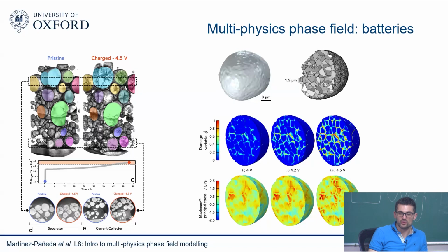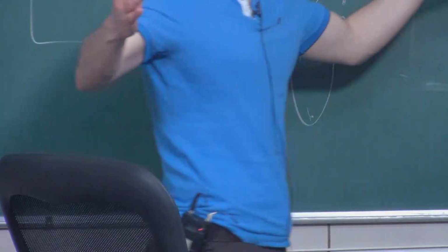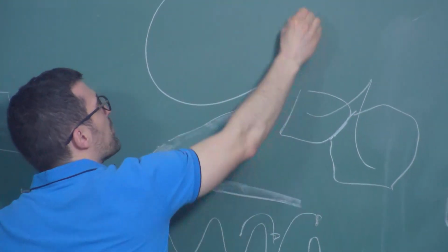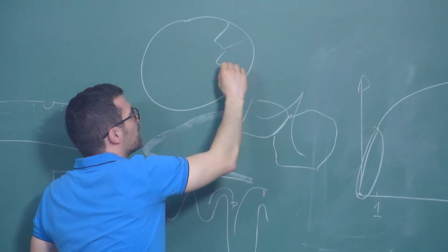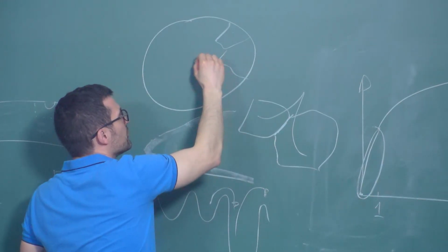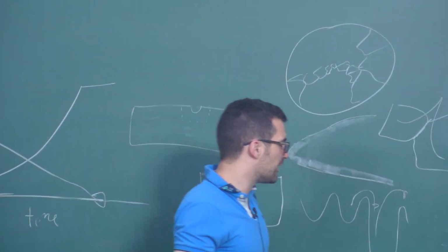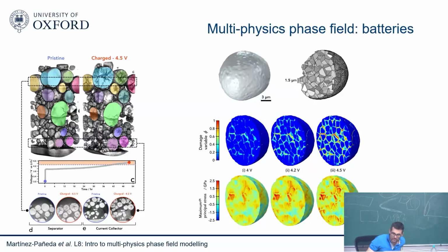There's also other people who have suggested the idea of using functionally graded microstructures. So the idea would be that the flux of lithium depends on the gradient of the concentration of lithium, which is very different, so the chemical stresses that you're going to get are very different. So some people argue that maybe you need, imagine, small grains or big grains in the outer boundary, and then this will become smaller as you approach the center of the particle. And there are various approaches where people are trying different things. You can test all of these ideas quickly with this model. This is the idea. So again, trying to understand safe regimes of operation and trying to develop a tool that, by resolving the physics of the problem, allows you to test ideas quickly.